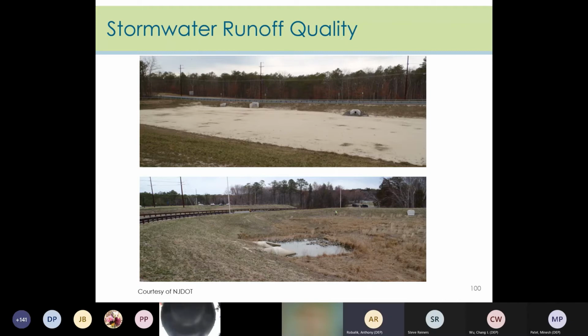So here's an example of two infiltration basins. The top one is functioning correctly. The bottom one has ponding at the inlet locations, and there's a lot of vegetation established. The outlet is over on the far right of the vegetated basin. This is a pretty big basin, so one question is, how will compaction from vegetative maintenance impact the ability of the basin to infiltrate? Additionally, vegetation is breaking down in standing water, and it forms a biofilm that can cover the sand layer and greatly reduce the basin's ability to infiltrate.